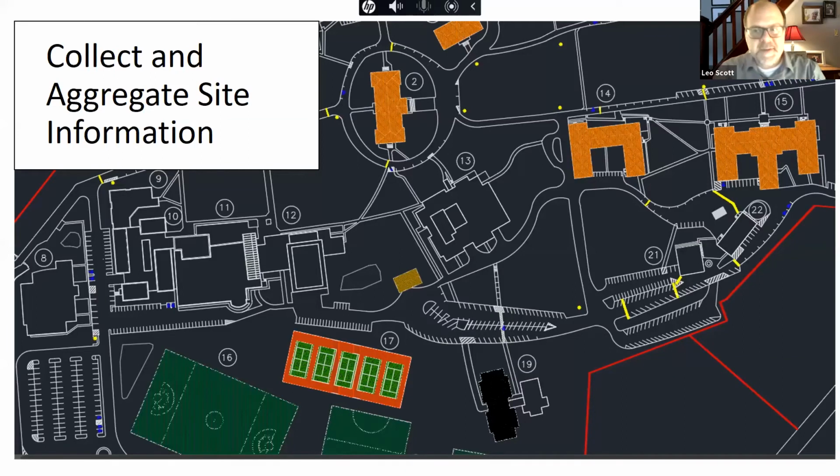So the first step, and this is a similar first step for almost all of these applications, we had received, I guess, 3 or 4 CAD files for the campus itself. And these CAD files were mainly drawn in paper space, so we're talking about XY coordinates on a page and not on the earth. So one consideration is we create the space map by aligning it with items we can find on the surface of the earth. Once that information has been aligned, the CAD data itself is theoretically copied and pasted into the GIS framework to create our base map.